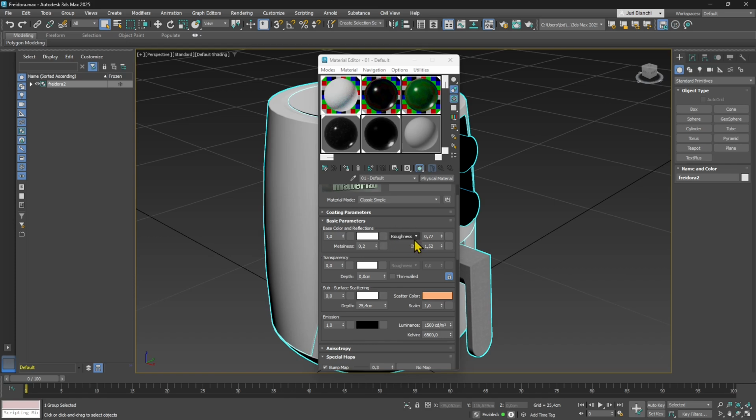Now, it's better to use roughness rather than glossiness, because PBR materials usually use roughness, metalness, and the diffuse or base color. So these are the three more important. Then we have also other maps, but we're going to just play a little bit with these three right now.